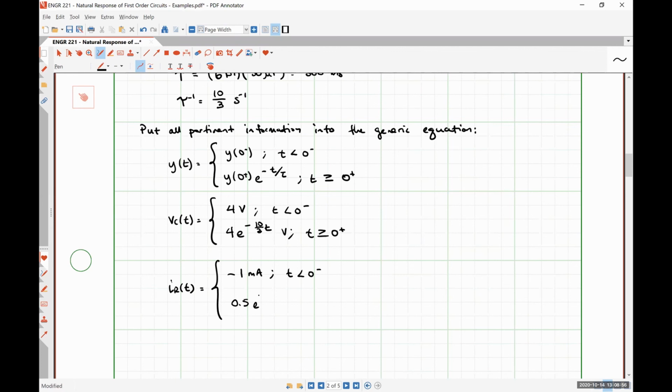And it will have the same exponential decay as the voltage. So everything is going to decay at this rate defined by the time constant, regardless of whether it's the voltage drop or the current through the capacitor, resistor, etc. It's all going to decay in this exact same way, or be a constant value of 0.